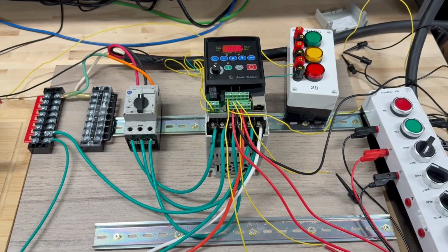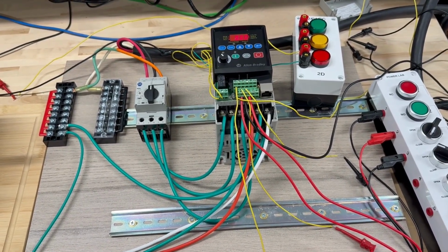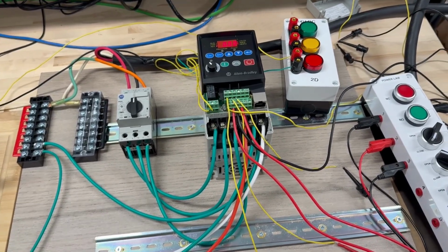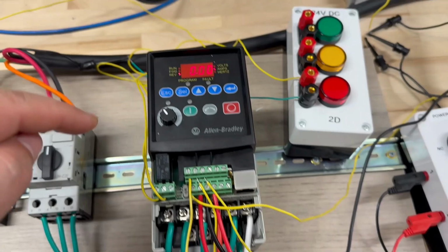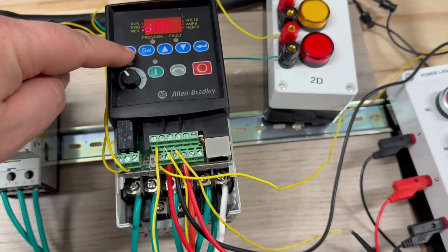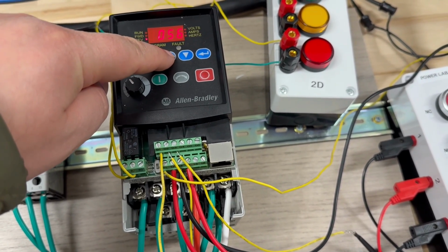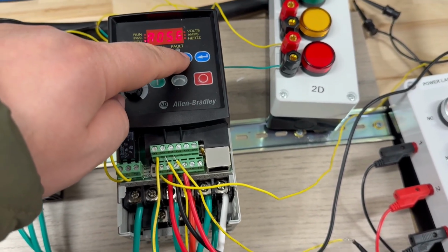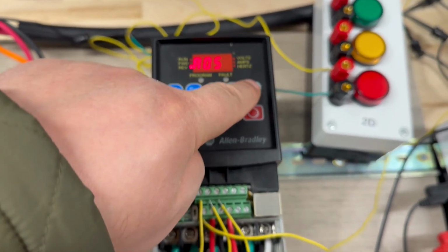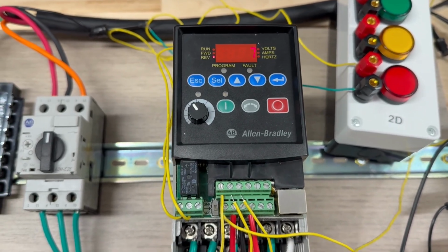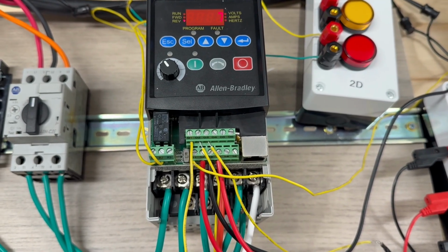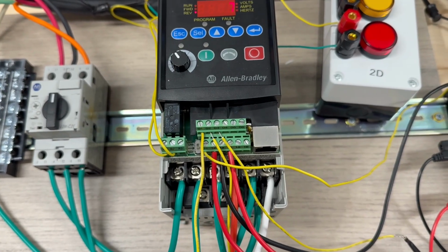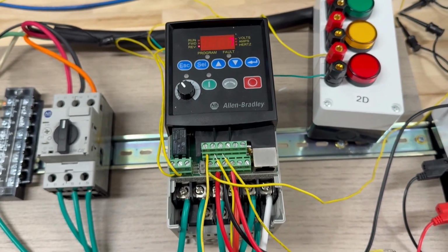Okay, so the next parameter in A55 is number 7, which is above current. Let's adjust that and see what it really does. So I come here and choose A55, enter, and I put in 7. Now you should give the current that it goes above, and then the relay should turn on.